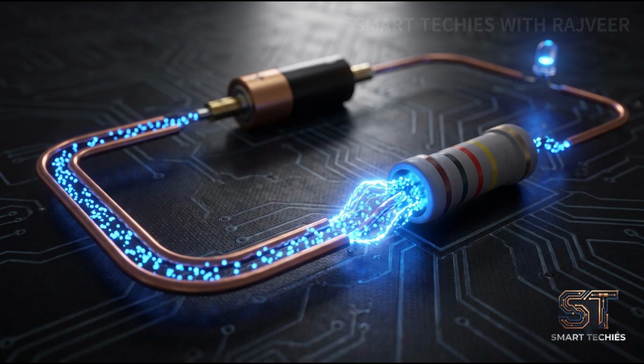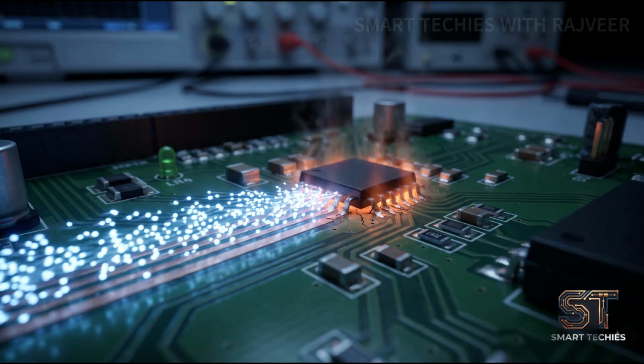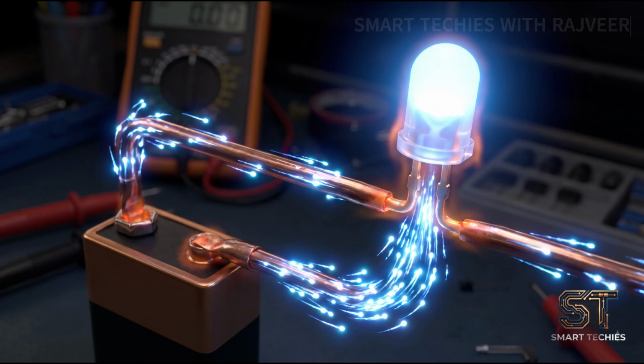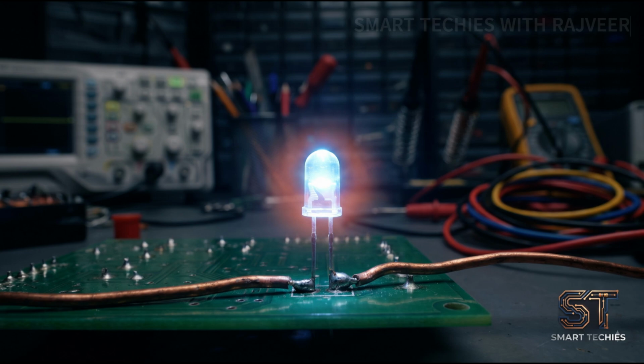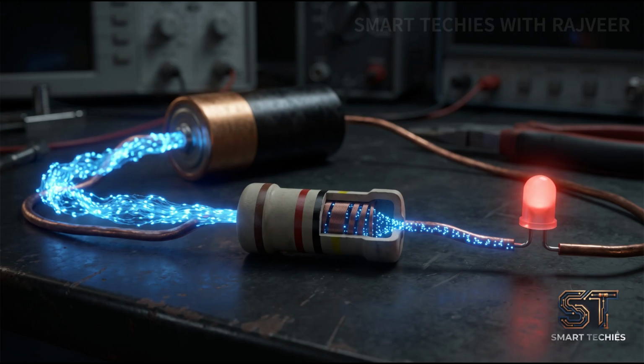Now you might ask, why would we want to make electricity harder to flow? Because sometimes too much current can damage an electronic component. For example, imagine connecting an LED directly to a power source. Too much current could flow through the LED. The LED may get damaged. So we add a resistor. The resistor limits the current and helps protect the LED.